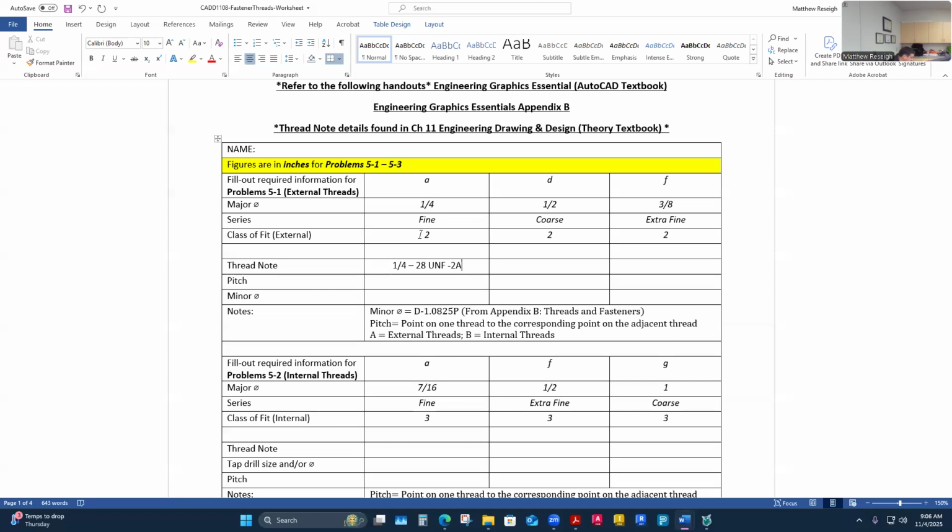And then they even go on to step H in our book. This location is for internal thread depth or external thread length in inches. This space is left blank when the drawing clearly shows. So anyway, your thread notes can even get bigger than what we've got. What I would call our standard thread note has these three columns to fill out, and sometimes even the third one is dropped.